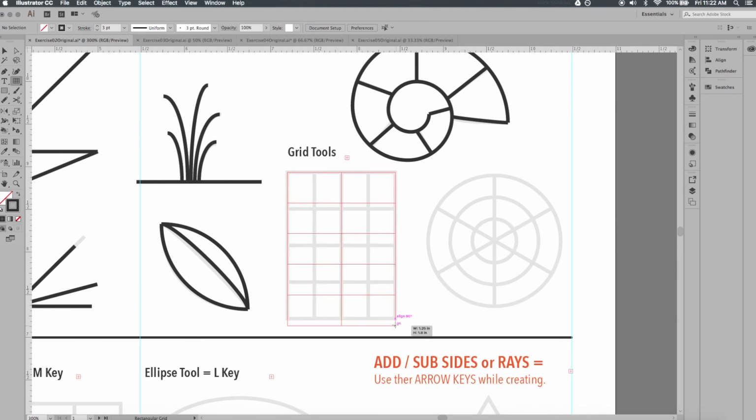Now this tool works by live numeric control, so I'm holding down on the mouse key, but I can see right here that I need more columns and I think I need one more row. To get more rows, I'm going to hit the up arrow key, and you can see as I do that, it's adding more rows. If I hit the down arrow key, I'm going to subtract the number of rows. I could go all the way down to 0 and have no rows at all, and I'll go back up again.